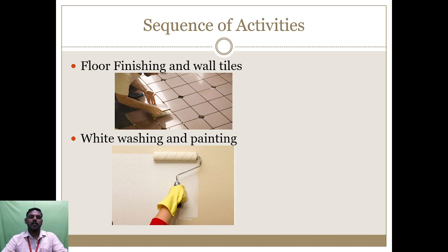While providing a floor finish, it should support in both ways: the water is protected from penetrating the surface. Next, in the bathrooms, the skidding nature will be stopped by providing rough finish or matte finish floor tiles. Wall tiles used in the restrooms protect the surface cement mortars from moisture movement.